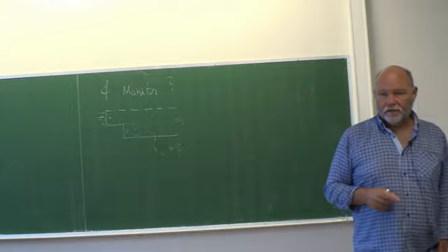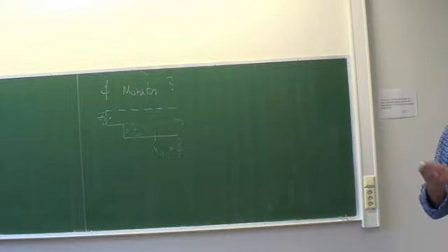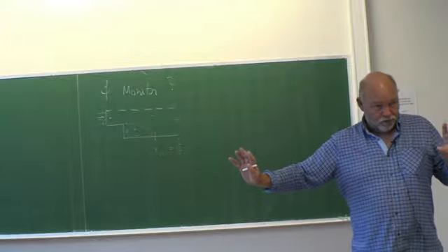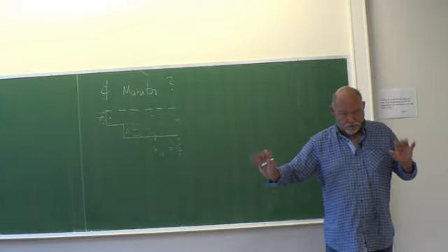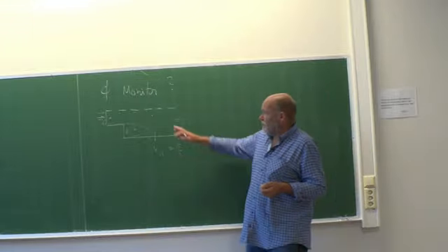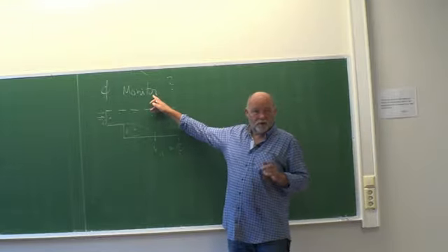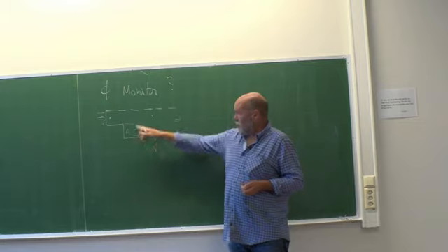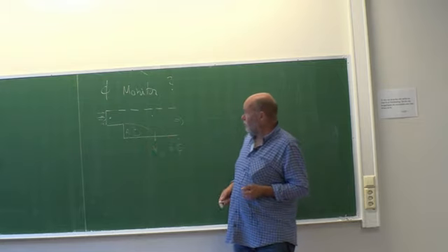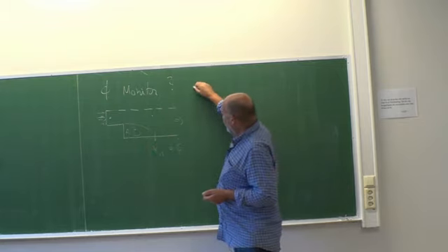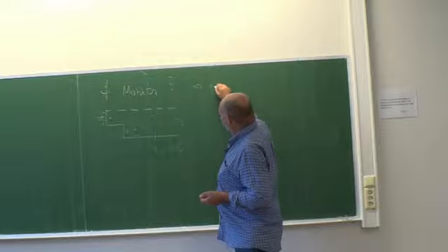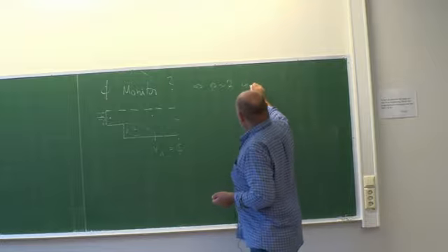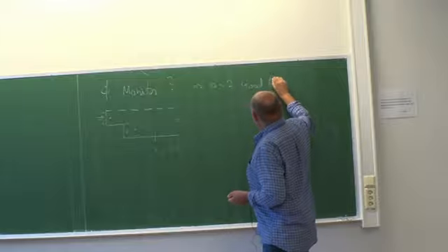So you see, when you do this procedure, you may have to look at 3 different solutions on 3 different meshes, and then start looking around for a good monitor. You may try several times. If p is around 2, that is a good monitor.